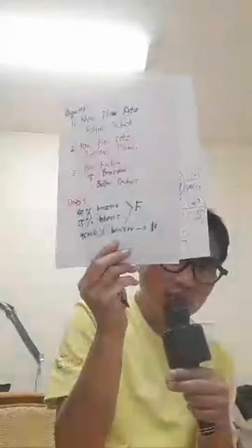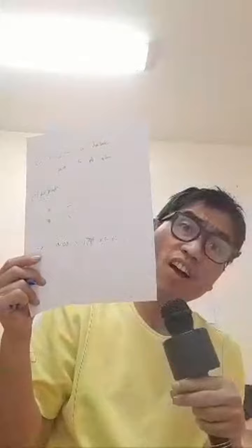Okay? So apply the component balance, because it is general for the whole bottom product. So you apply the component: 0.08 times 1774 times 0.45 mass percent of benzene in your feed. That becomes your bottom product. Okay? Did you get it? So automatically that is your bottom product, the condensate.